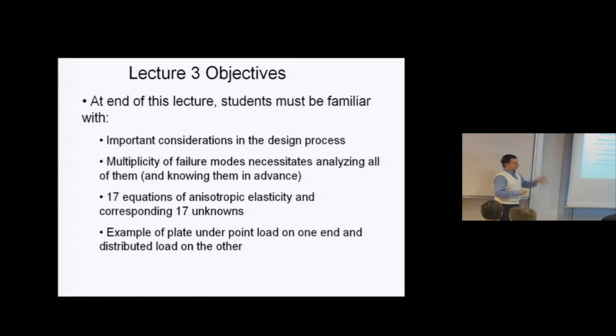In composites, it gets much worse. There are many more, and you can anticipate that by thinking about the fact that you have fibers and matrix, and either of them can fail, or the interface between them can fail, and then in sequence can trigger different types of failure modes, and that, as a result, makes it more complicated, more challenging, and more interesting.